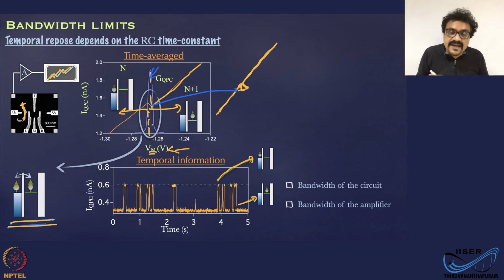And this is the real data, where you can see a two-stage signal, ups and downs only, which represents the tunneling events of the electron between the dot and the reservoir, in a random manner. It's a random telegraph signal because this is driven by thermal fluctuations, thermal energy. Whenever the current is high, the electron is outside, and the lower level shows the electron is inside.